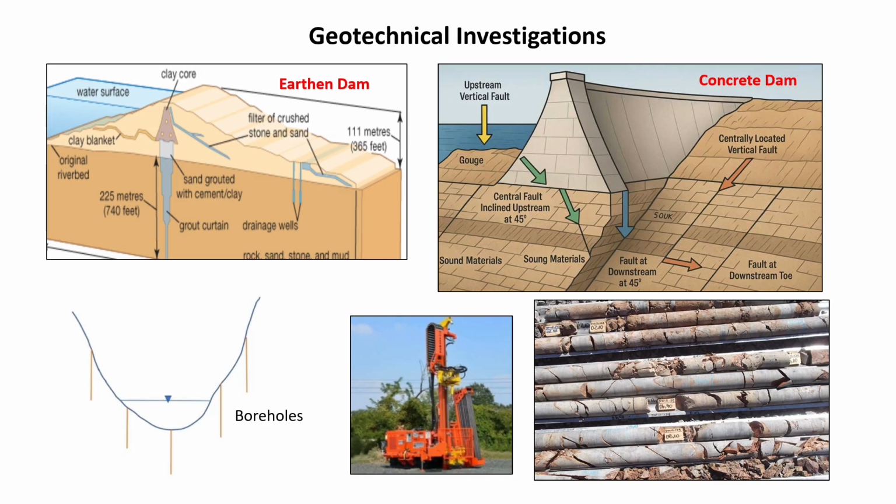While doing the boreholes we have to collect the core samples as shown in the right bottom image. These core samples indicate the variation of geology along the depth. While doing the boreholes, we also have to do the water permeability test to know how the water is seeping